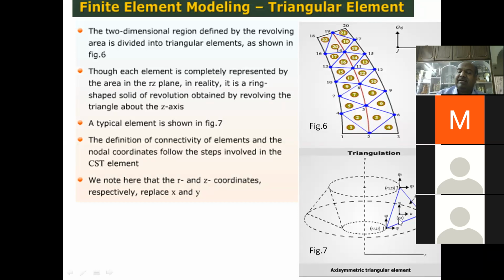Then you have the global coordinate anywhere as r, z. And here your displacement measurement could be Q at r or Qr, Qz, we can say. So the displacements you have 3 in radial direction, 3 in tangential direction. Then each node you can have 2 degrees of freedom of translations only.